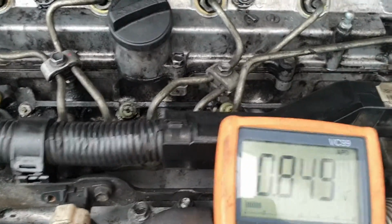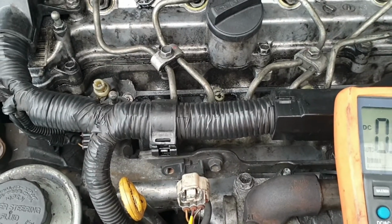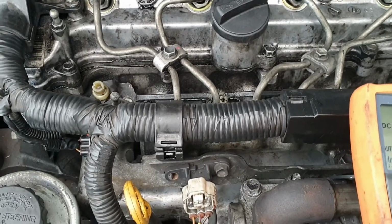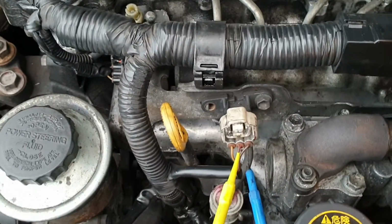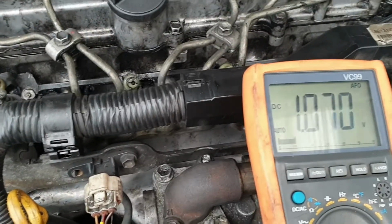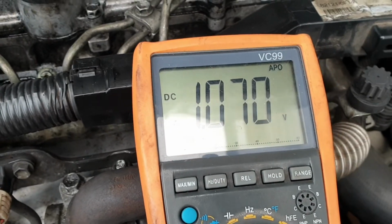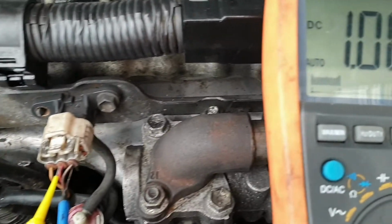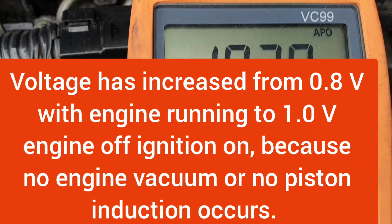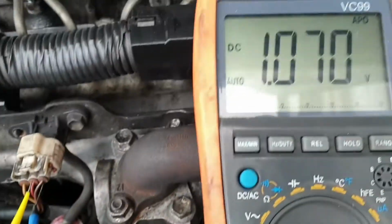Now I'm going to turn the engine off, ignition on, engine off, and take the value of the sensor signal wire. So now the ignition is on, the engine is off, and the value of the manifold absolute pressure sensor signal wire is 1.070 volts.